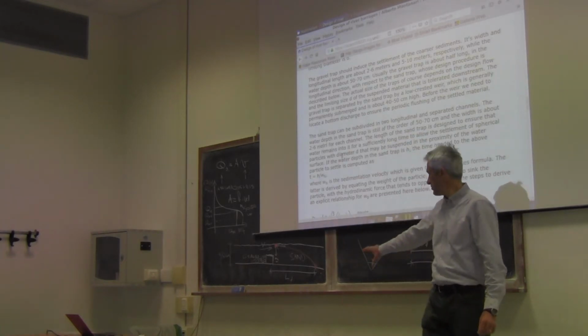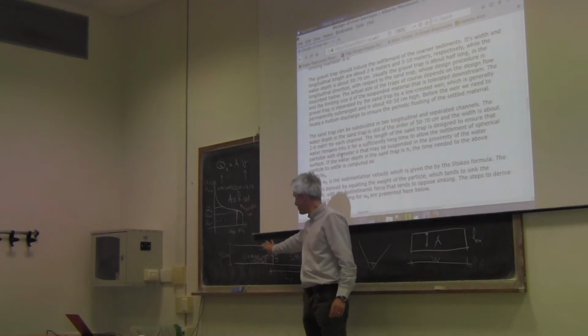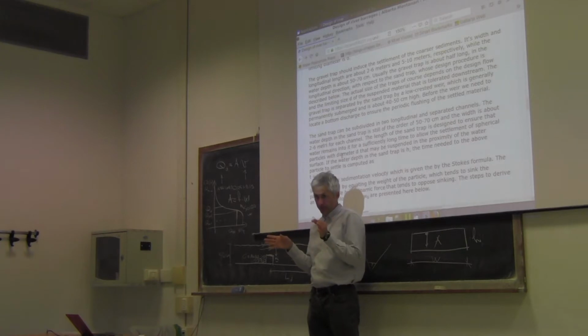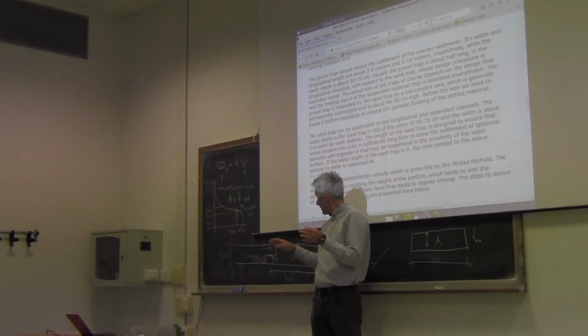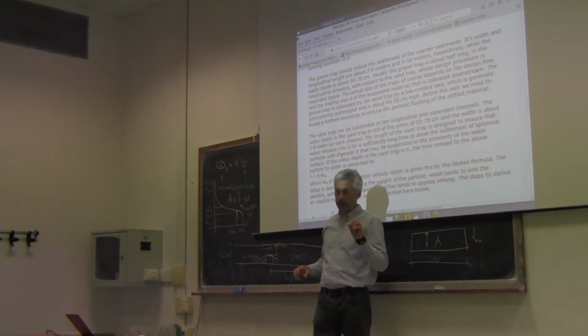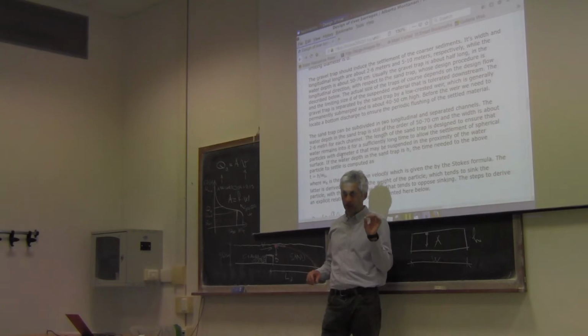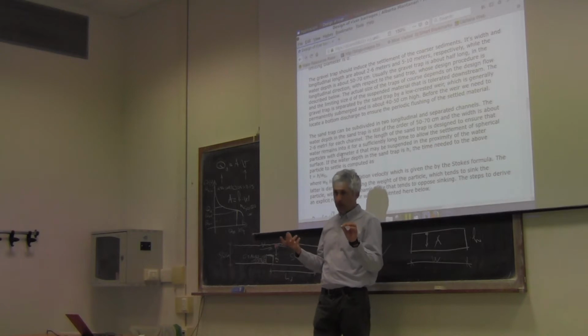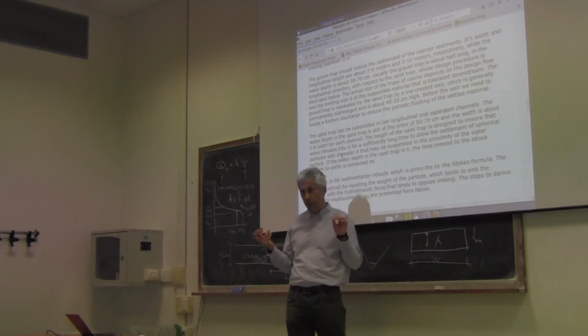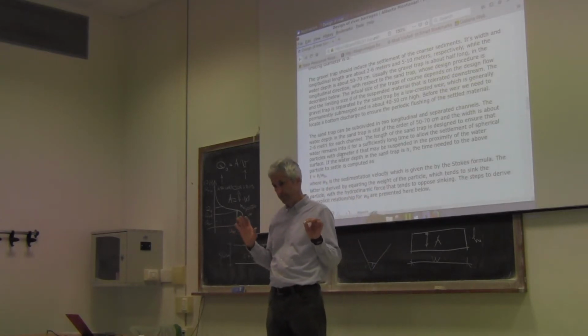This is a simple physical problem. This is a simple study of the movement of a rigid body. The rigid body is a particle. We know the horizontal direction. We need to know the vertical direction. The vertical direction is that of a gravel particle which is immersed into water, subjected to gravity. And you know that this vertical velocity can be computed with the Stokes formula.